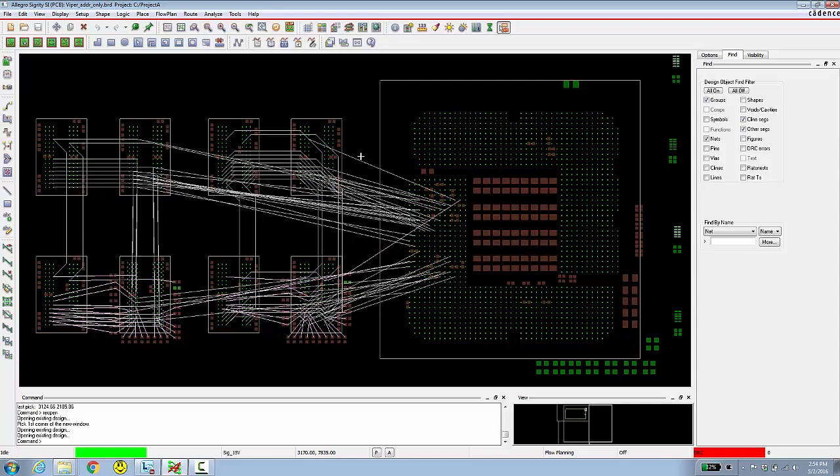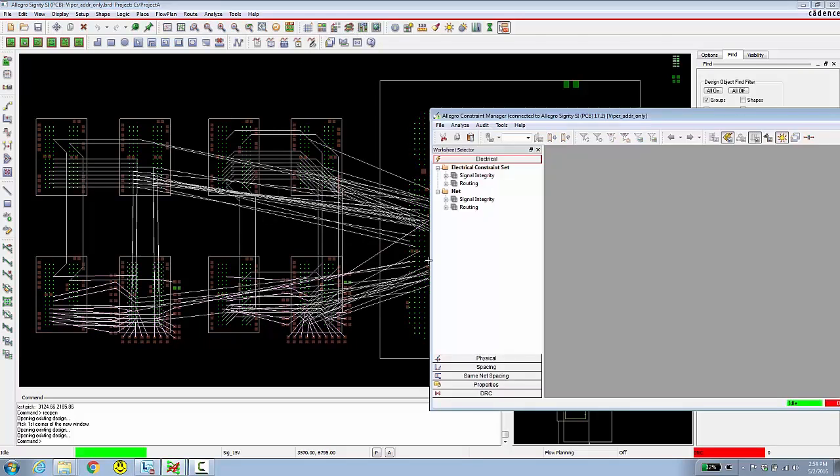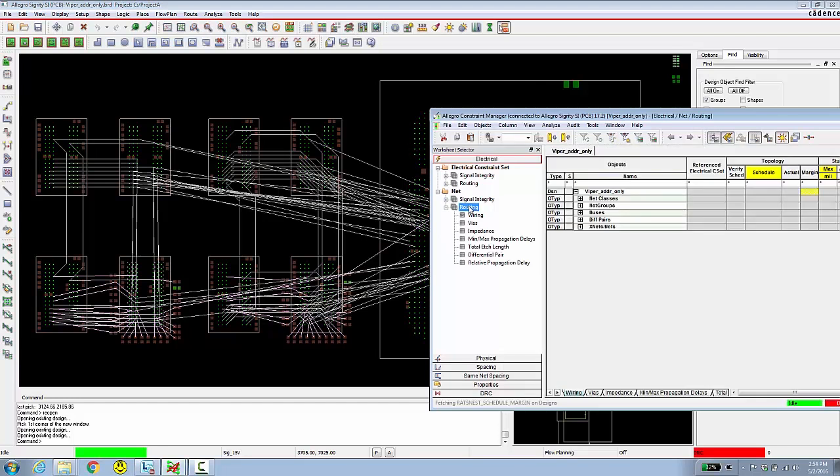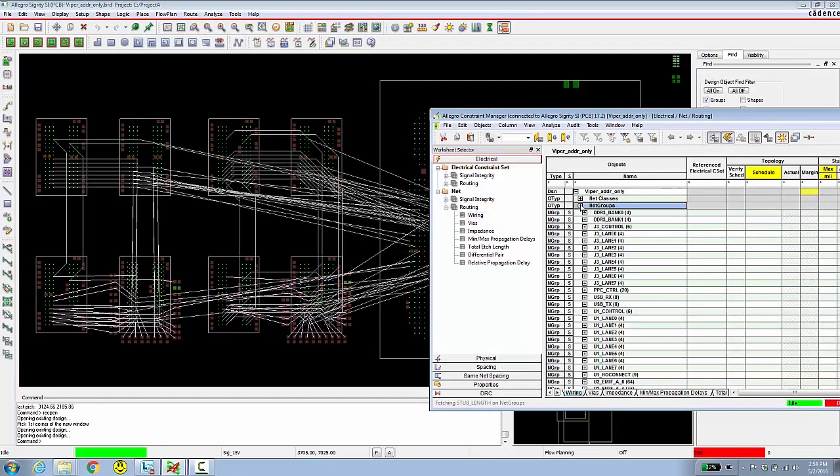Because of this, you may need to schedule some of your nets that contain multiple pins. There is no fixed order to this. You can schedule first and then create your rats bundles, or you can create your bundles first, and in some cases, it will then be obvious that a topology schedule is needed.